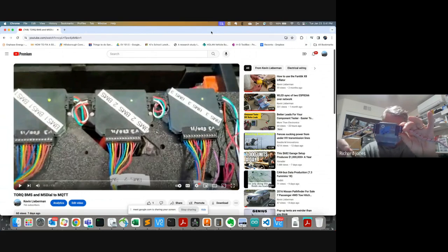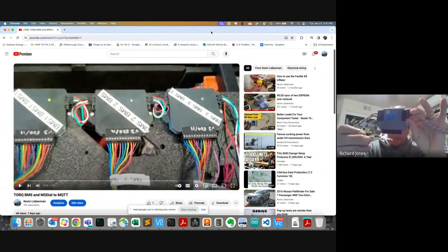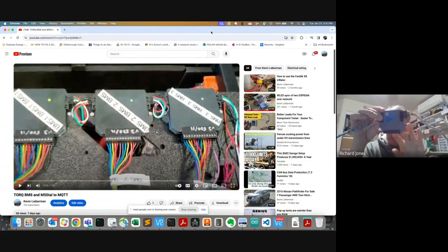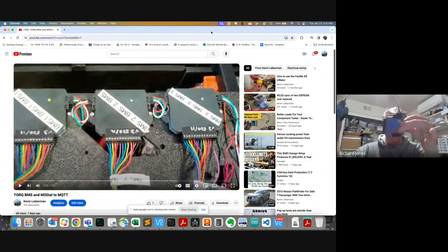And then this guy here is a current sensor, a little thermistor. So the little BMS board can read 12 cell voltages that are connected here and 2 thermistor values, which you'd bind onto your terminals or somewhere like that. And then through CAN bus, you can read the voltages and the temperatures off each one of these modules.